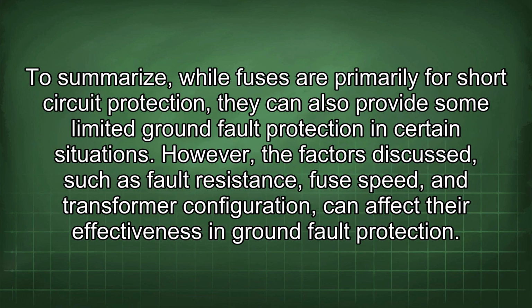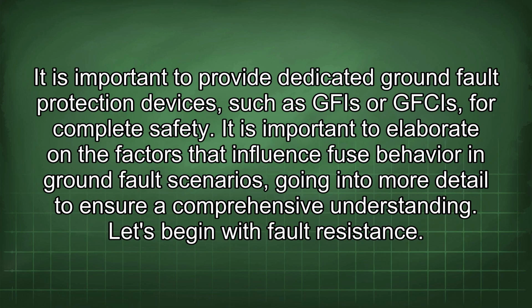To summarize, while fuses are primarily for short-circuit protection, they can also provide some limited ground fault protection in certain situations. However, the factors discussed, such as fault resistance, fuse speed, and transformer configuration, can affect their effectiveness in ground fault protection. It is important to provide dedicated ground fault protection devices, such as GFI or GFCIs, for complete safety.